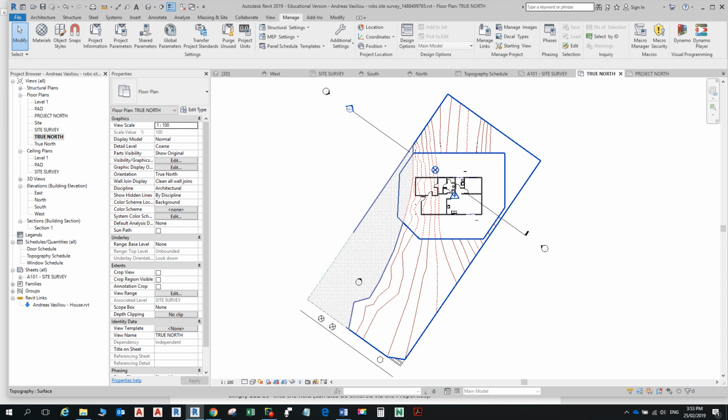Yeah. One important point I think to say at this point in time is when you look at Google Earth, you'll see that the north is this direction, down. So where this block is and contact to the road, you get that north from Google Earth, you'll find that it's down there. So you have to find it to make that true north. Yeah, right, rather than what the site plan is.